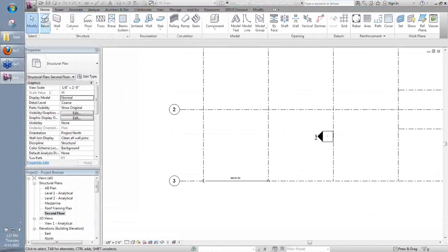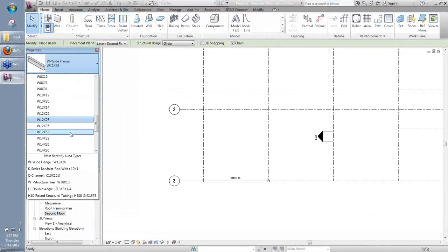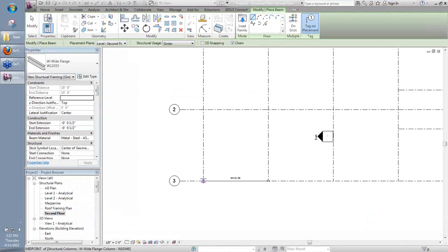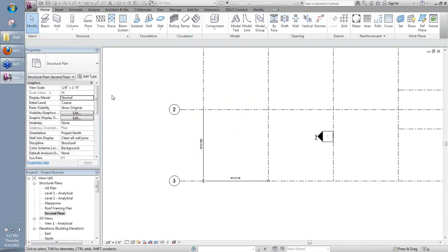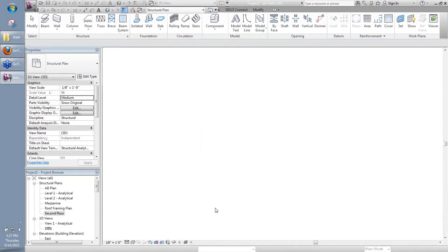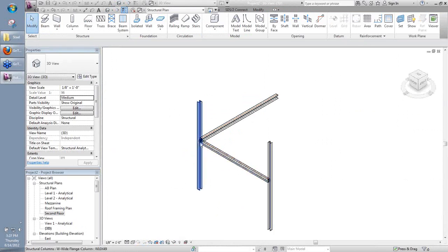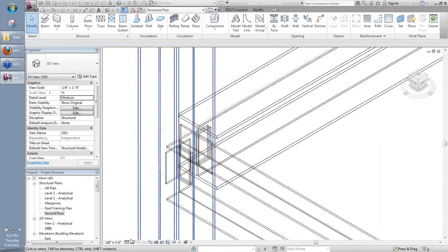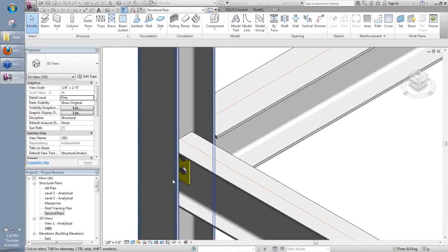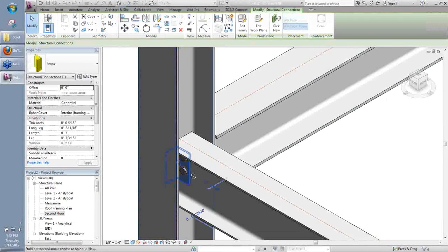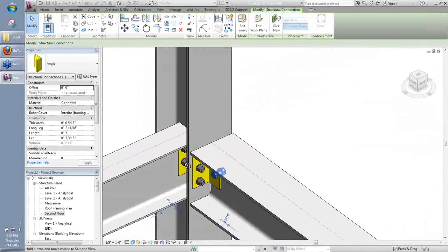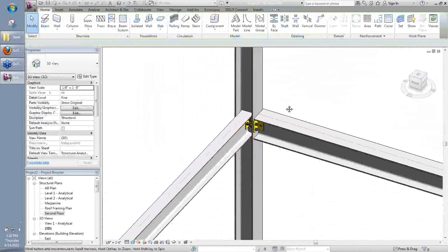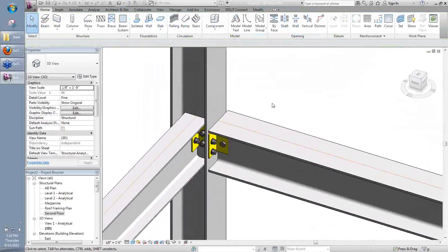okay, I go ahead and add the beam. Since it's already modified, I don't have to wait for it to modify all those wide flange families again. If I go to the 3D view here and show you, we can see everything's being designed there already. So again, by running that library feature, we're modifying the default families rather than just the ones loaded into a particular project. We don't have all that wait time then.